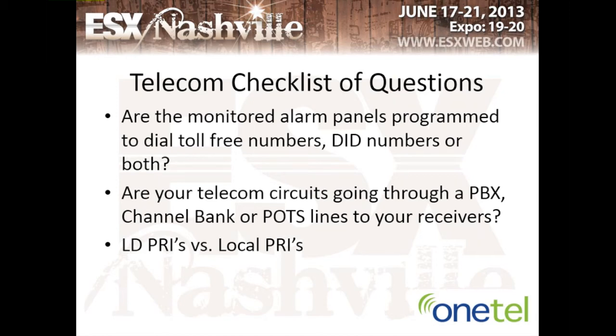So, are the monitored alarm panels that you're monitoring programmed with DID numbers or toll-free numbers or both? That's going to make a big difference. Are your telecom circuits going through a PBX or channel bank or POTS lines to your receivers? Some central stations have multiple. Some are doing just PBX, some are doing just channel bank. I've seen all different versions of that.